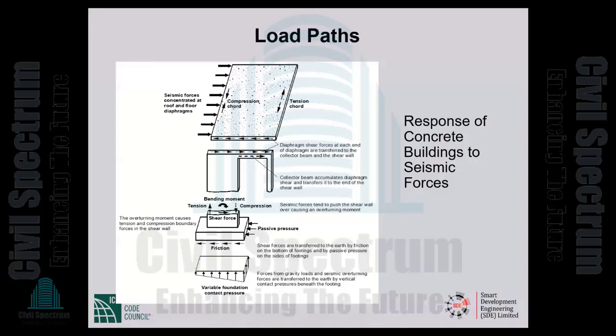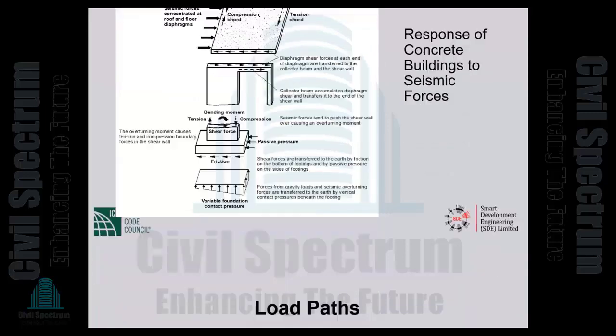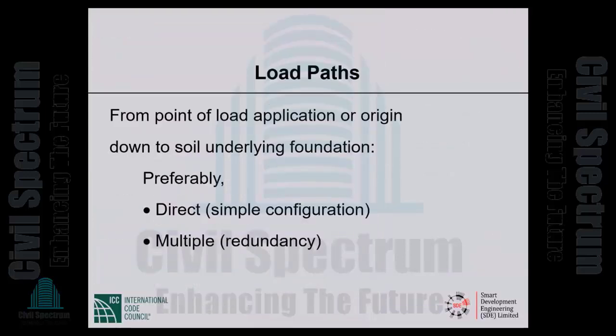Okay. So earthquake engineering really, in its essence, consists of taking the inertia forces from where they originate, namely the floor and the roof diaphragms, down to the ground underneath the foundation, where all forces belong. So we have to provide load paths from point of load application or origin down to soil underlying the foundation. This is what the engineer has to do.